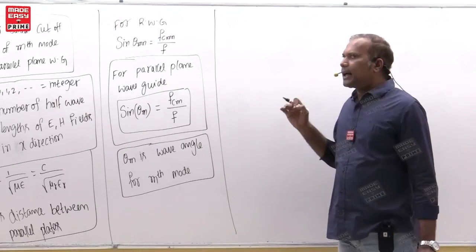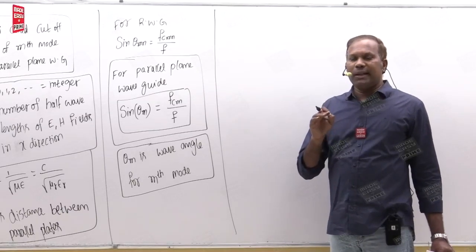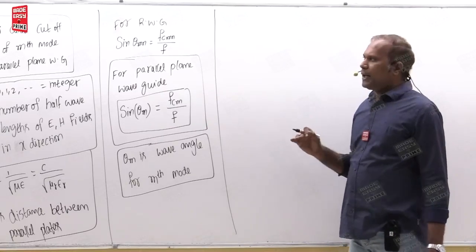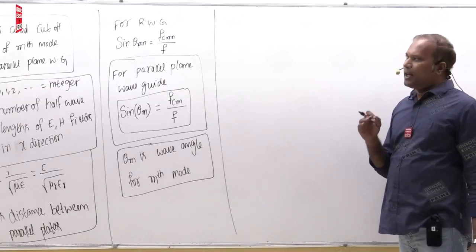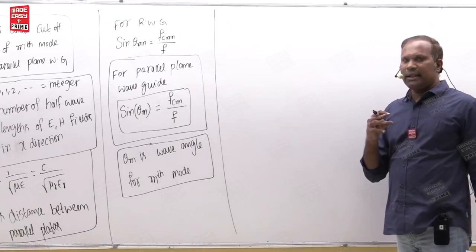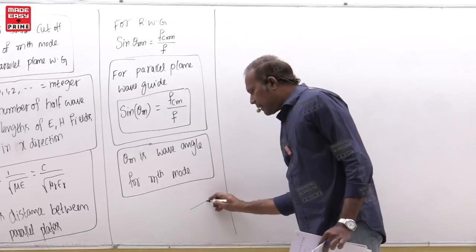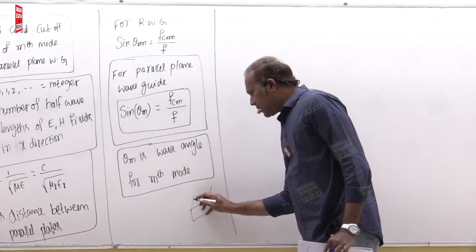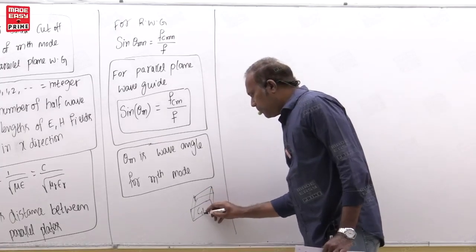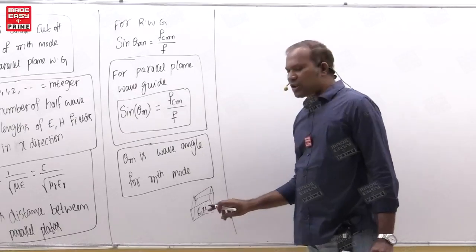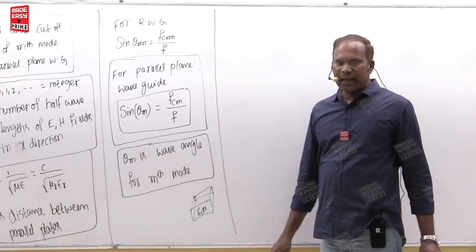That is why already in the rectangular waveguide you have seen the cutoff frequencies are in the range of gigahertz. So that is why using rectangular waveguide, rectangular cavity is manufactured, and that stores energy, because inside the rectangular waveguide, that medium is there. That medium has parameters called epsilon and mu, and this epsilon stores energy, that is called electric field. Mu also stores energy, that is called magnetic field.